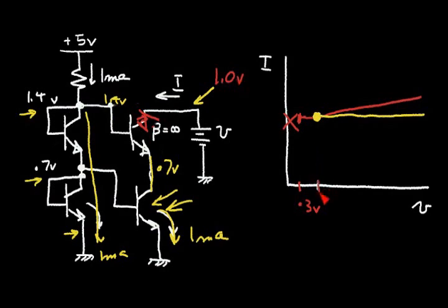So this current source will have an operating range here of about 1 volt. I don't want to operate it in this range. So I've lost some voltage margin on my current source, but I've gained a very constant current source. And sometimes that might be useful.